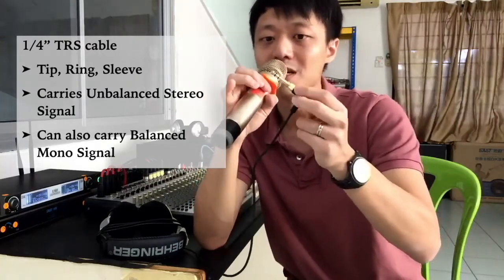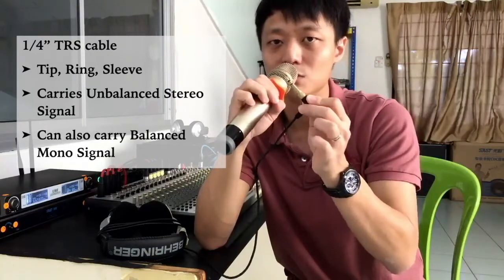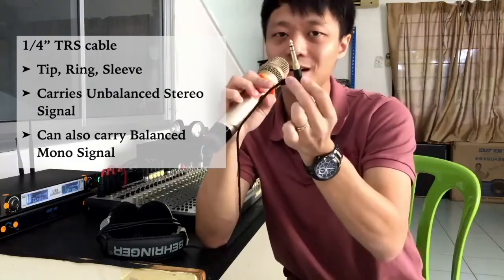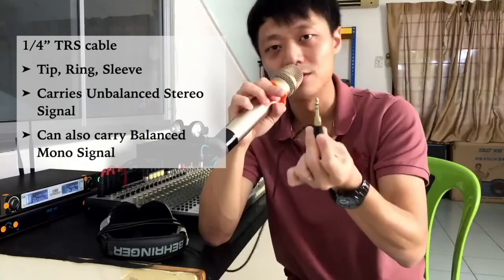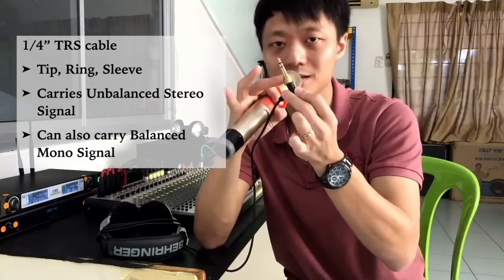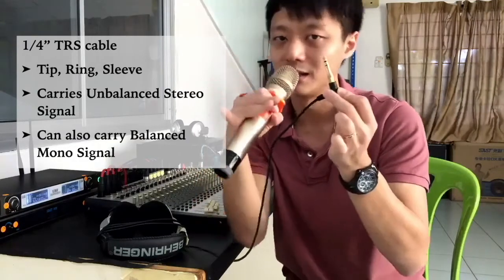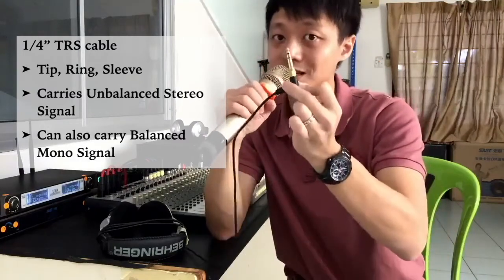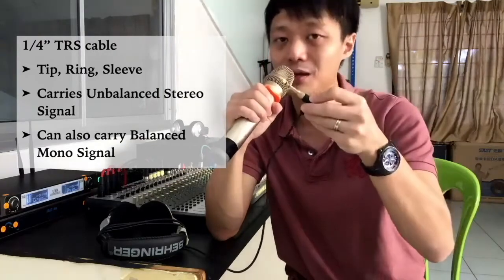The tip usually is used to carry the left mono channel. The ring usually is used to carry the right mono channel, and then the sleeve is for the ground. So in this kind of configuration, you still get unbalanced signal because it is stereo unbalanced. One is left, one is right, and one is the ground. So it's stereo, but it's unbalanced because you don't have a positively charged and a negatively charged signal going together in a cable. However, you can also use the TRS 1/4 inch connector to carry balanced signal.